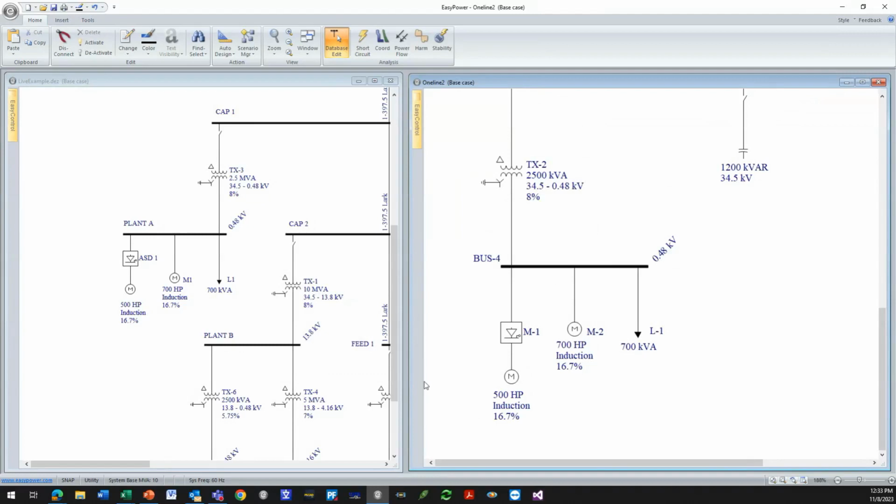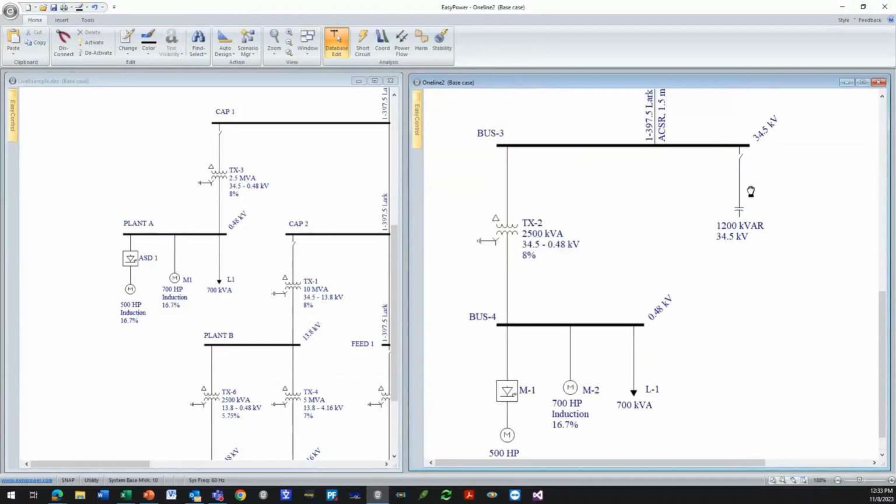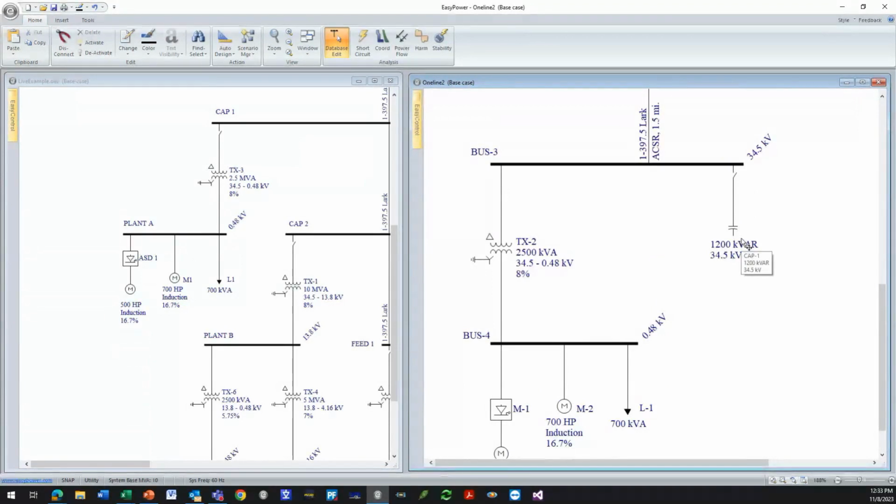Oh, you see that I've built this part of the system. I'm missing my spectral content. I got a capacitor bank in. Important: you must model every capacitor bank on a system. Just don't try to skimp. You'd be surprised where these will manifest and cause problems.